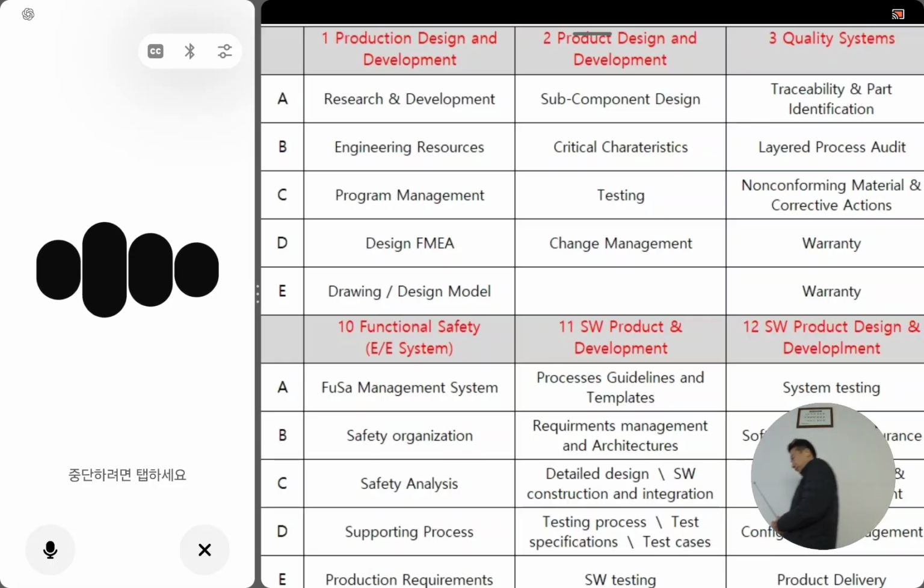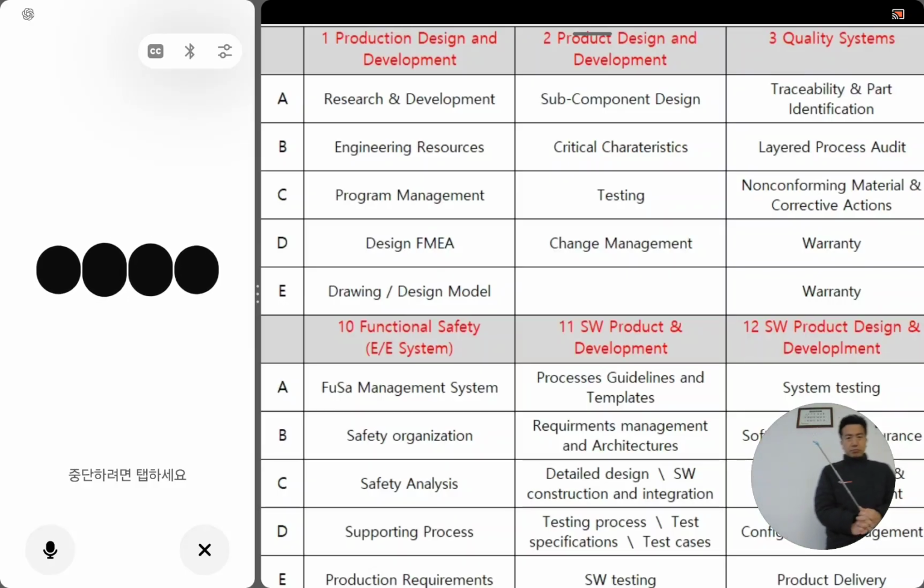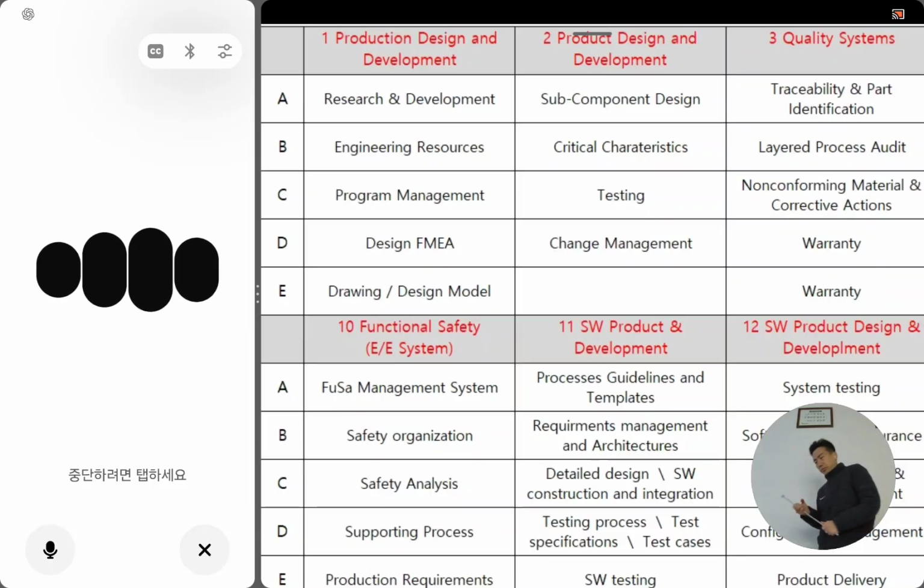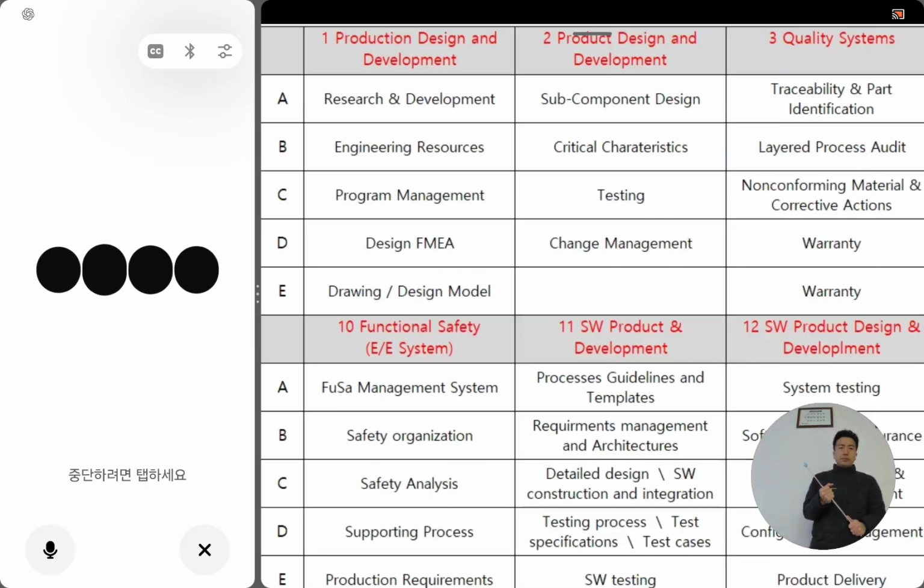Control means who approves drawings, who releases them, who can change them. Traceability means can I trace requirements, CAD, drawing, BOM, manufacturing. Usage means is this actually what production and suppliers are using, or is it just stored somewhere nicely? Every serious audit question comes from one of those three lenses.